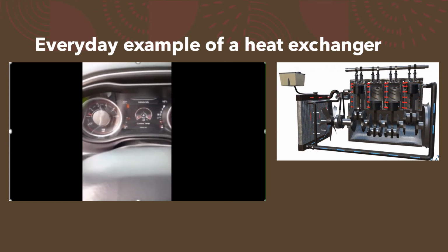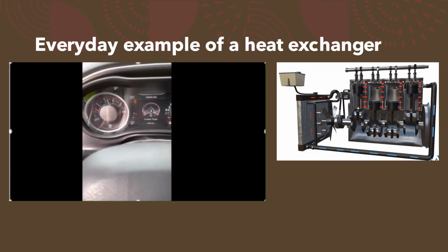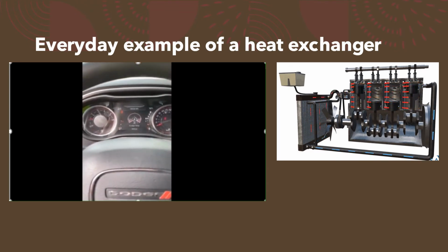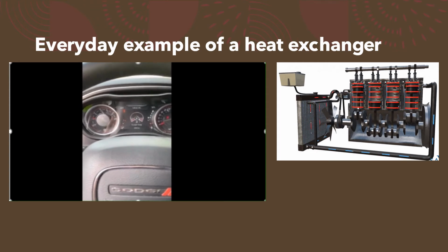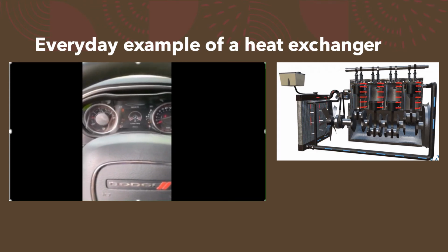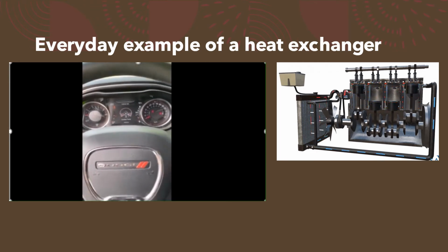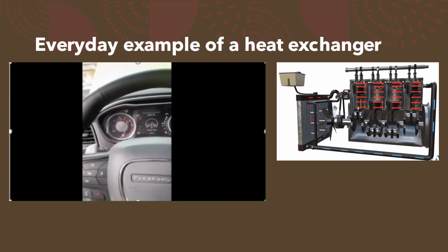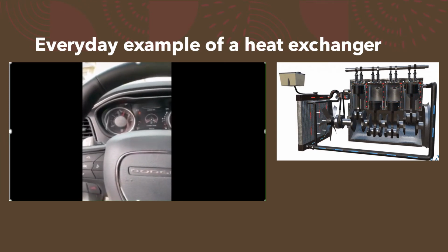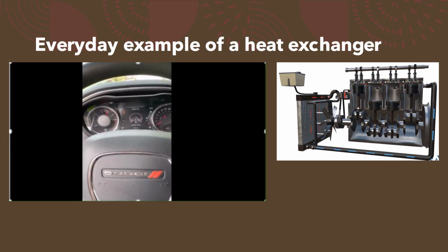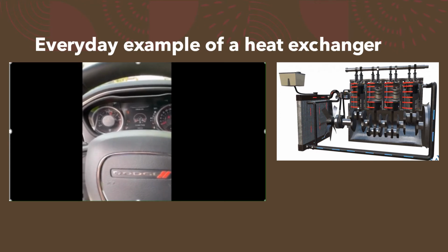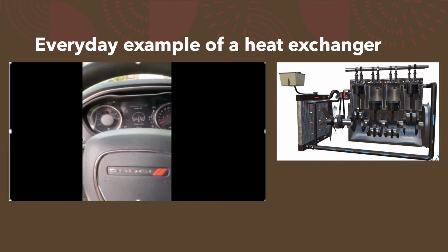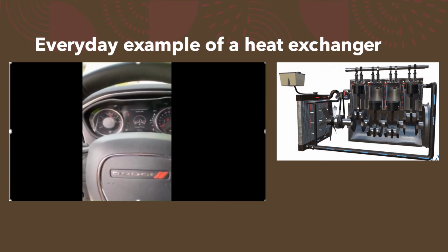So as we can see in the video, we have a coolant temperature on the dash, and we are using a thermometer to measure the engine temperature. If you look to the right, we have a little diagram showing the process it goes through. As the motor is creating heat, you can see the coolant flowing into the top of the motor. The coolant will then take the heat produced by the motor, and as it circulates and reaches temperature, the thermostat